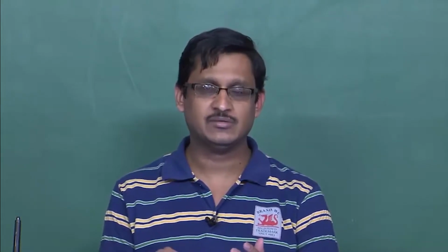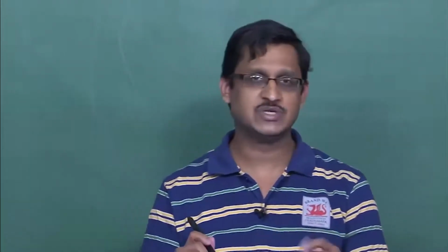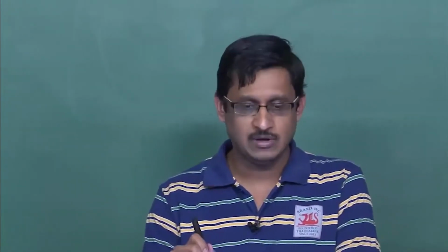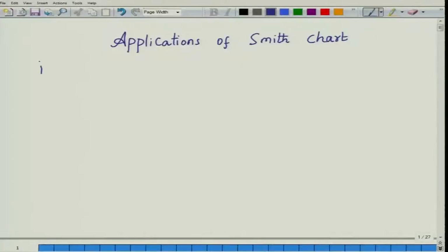That way you will be able to understand how to use Smith chart to solve the problems that we are going to discuss. So we begin with basic use of Smith chart we have already discussed. What we will now do is to see what type of problems Smith chart allows us to solve. One typical, very basic application of Smith chart, is to find the impedance of a load that is connected to the transmission line but at a position away from the load.